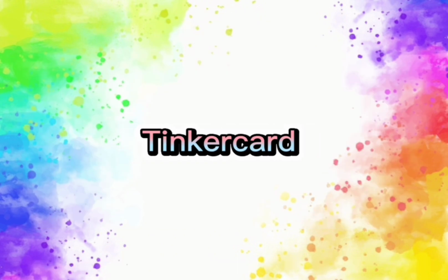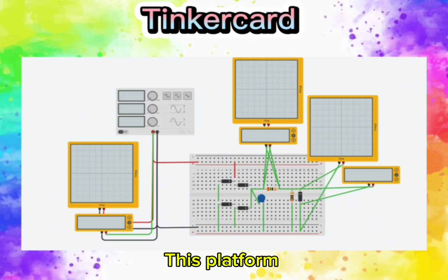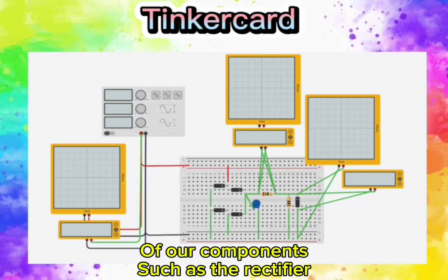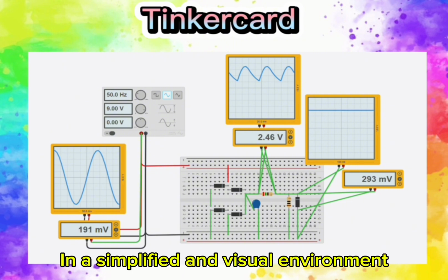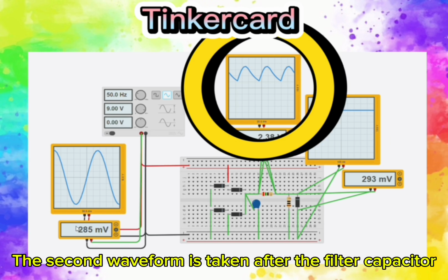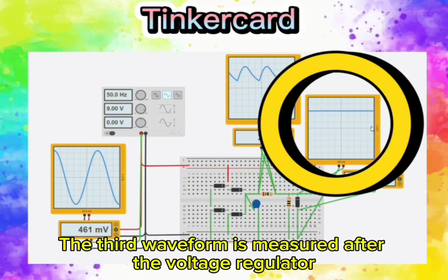Now, we will present the simulation results of our circuit using both Tinkercad and LTSpice to analyze and verify our design. Firstly, we use Tinkercad to simulate the basic behavior of our circuit. This platform allows us to quickly test the functionality of our components, such as the rectifier, filter, and voltage regulator in a simplified and visual environment. The first waveform represents the AC input voltage. The second waveform is taken after the filter capacitor, and the third waveform is measured after the voltage regulator.